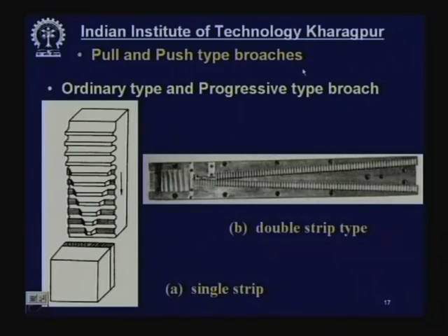But if it is a push type, then there is a chance of buckling. So, push type broaches will be smaller in size, more rigid and subject to lighter cut, and they will be used for outer work. Now, here you can see